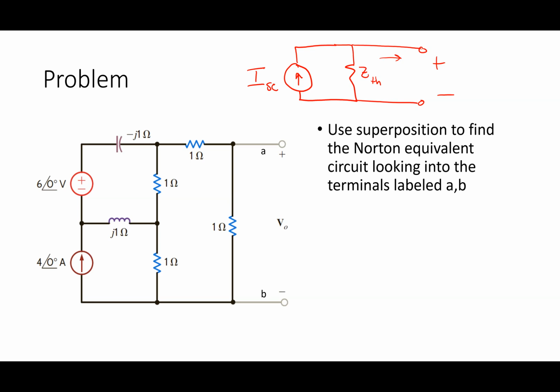The load source. So if I connected a source across the terminals, Z Thevenin would be the impedance seen by that source. And it's the impedance seen by that source, meaning what we do is we turn off all of the sources inside the network and say only basically what is the load current doing? What impedance does it see? What voltage would it create if I had that current source there?